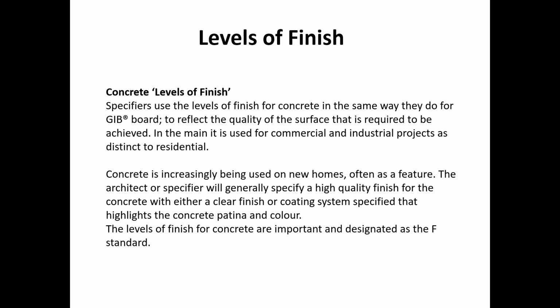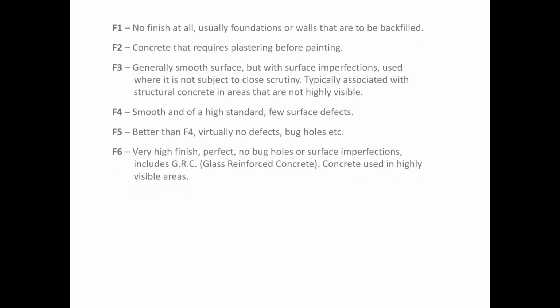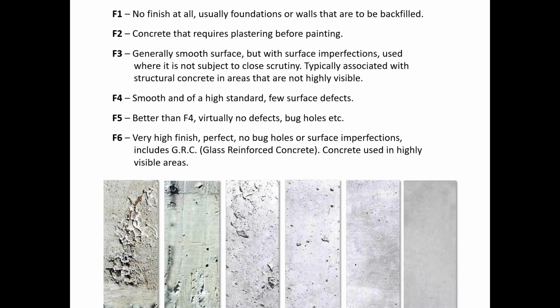So it's called levels of finish, from the Concrete Association New Zealand. You can see the pictures down the bottom and the words at the top. That's in situ concrete, and as you go from left to right, it gets better and better. Now, a couple of things. To get F6, which is your absolute perfect concrete, you're going to spend a lot more time in the design and placing and finishing of it, but it's worth it. And you don't want to be getting the ones on the left unless that's an acceptable finish for you. All those bug holes aren't the best.